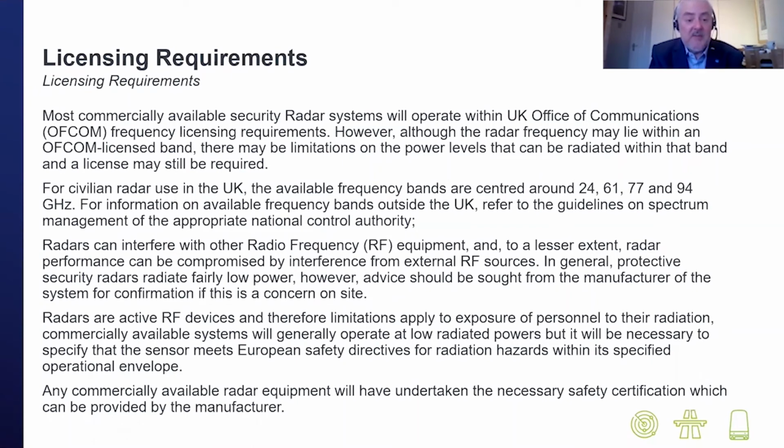Radars are active RF devices, so there are limitations applied to the exposure of personnel to their radiation. Commercially available systems generally operate at very low radiated power, as I've just mentioned, but it is necessary to specify that the sensor meets any European safety directives for any radiation hazards within its specified operational envelope. Ours are safe from a meter distance, even the most high powered radar that we do, and as they're generally up on a pole between 3 and 6 meters, that's not a problem. And any commercially available radar equipment should have undertaken the necessary safety certification, which can be provided by the manufacturer.